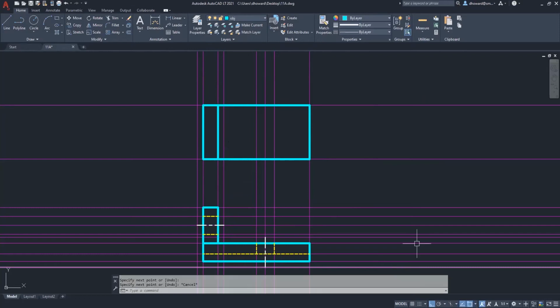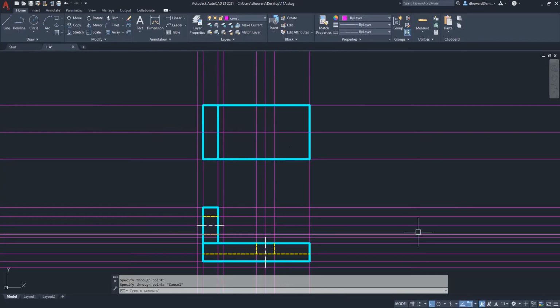And all right, so what else? How about the center lines for the holes? So that's obviously in the middle. That should be pretty easy to draw. If I go to construction line, XL, enter, I should be able to just grab the midpoint. There it is. So I didn't even have to figure out what that was, although half of 2 1/4 is 1 1/8, or 9/8. Could have offset this line right here 9/8 to the center, but either way, now you've got the center line.